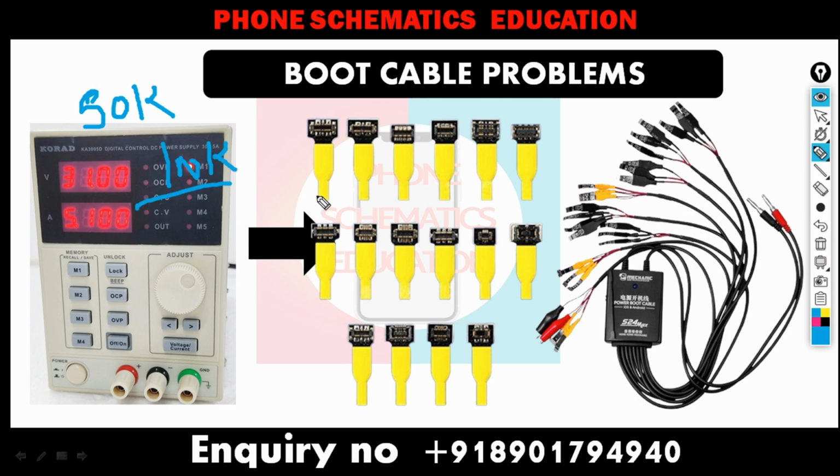So there is a difference, because R2 in the battery divider circuit gives a different output. That's why some phones don't turn on when you connect the boot cable. When you connect the battery and power up the phone, it turns on completely. But when you try to boot with the boot cable and a compatible connector, it's not turning on because of the circuit mismatch. I hope you get my point.